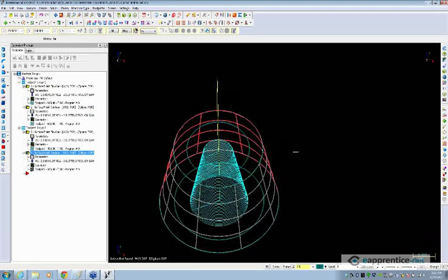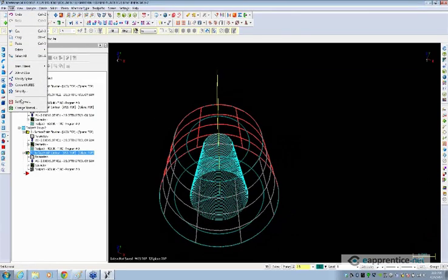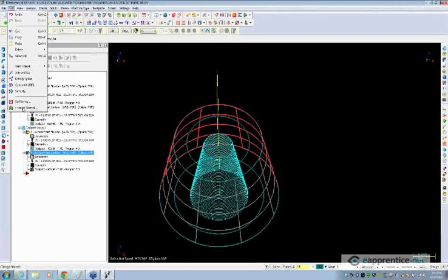There are two commands that you can use to change a normal. If you go to the Edit menu, you'll see Edit, Set Normal, and Edit, Change Normal. The Set Normal command is typically used with a group of surfaces, and it allows you to select a bunch of different surfaces, and when you use the command, the normal direction on the surfaces will try to be set to be equal or near to equal to the Z direction of your current construction plane. So whatever tool and construction plane you've got active, if you use set normal, it will try to direct all of the normals of all the surfaces you've got selected towards that Z axis.